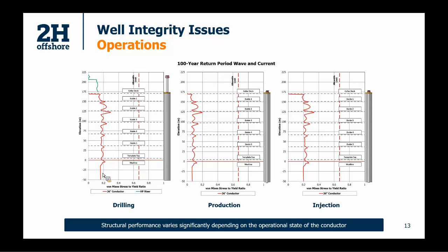The other thing that we're worried about is stability when it comes to conductors, and the way we approach stability is we do a calculation and we base it on an interaction ratio, where an interaction ratio greater than 1 would indicate a susceptibility to buckling. So if we look, we can see we analysed it for drilling and we have an IR of 0.731. So that's perfectly acceptable, it's under 1.